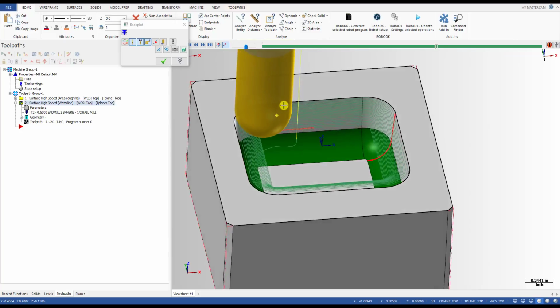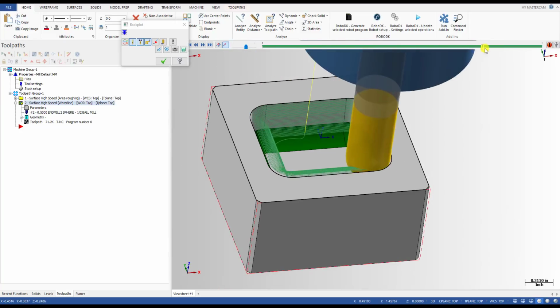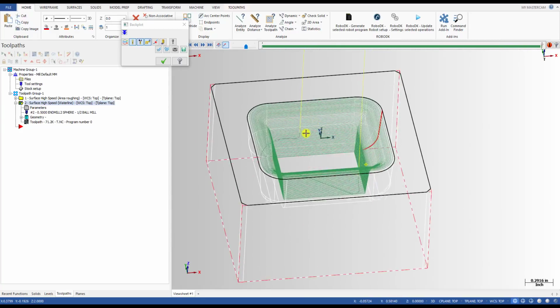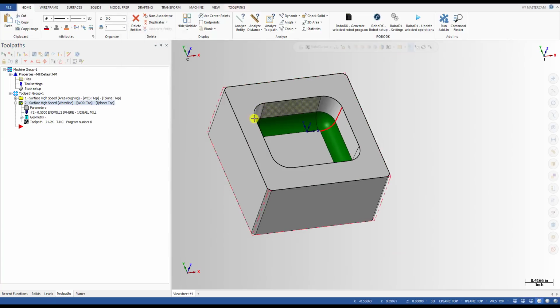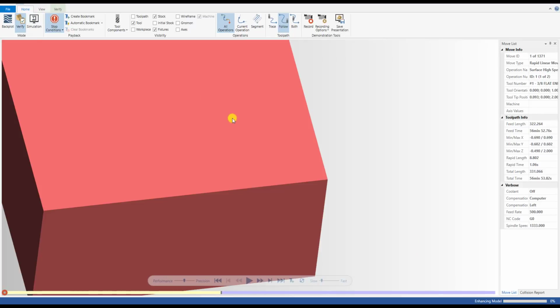So you can see I have this finish toolpath with a 1/2-inch ball mill. So this is our finish toolpath. It will look like this, and we can take a look on the simulation. Now you can see I use the tool that has a radius greater than the radius of the part here on this fillet, and now I'm gonna do the simulation so you can see what happened. I'm pretty sure you have it a lot in your machining.